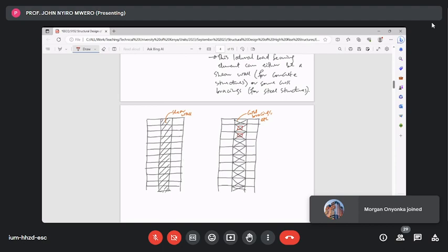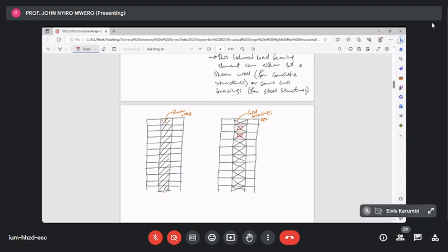Now, when you do bracings like that, then you start having a need to hide them, and because they are heavy structural elements, those structural steel UBs or UCs, it's difficult to hide them, so they become obvious. But secondly, they also become an obstruction such that you cannot have a clear view as would have been desired.